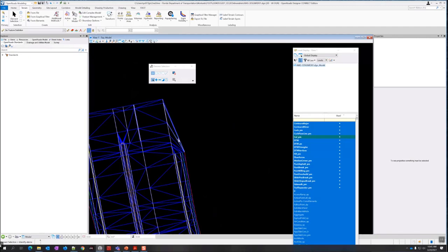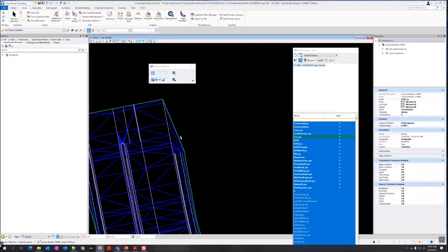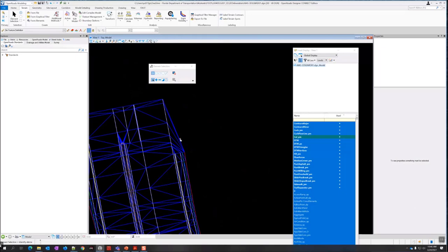So if I click on the terrain boundary here, we'll get this little pop-up and click on the ruler. I would just come down here and remove rule, which allows me to make edits now that I've removed that rule.